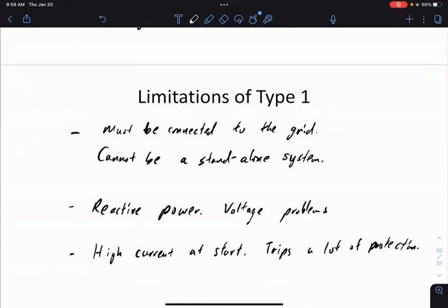Okay, so we have come a long way from these type 1 machines, right? This was really a proof of concept at that time, as you cannot put a lot of them in the system. Good. You can't create line power from a different one, right? You still need a reference. Right, you need a reference that's fairly constant. It can't just be another wind turbine, because that's also changing. So it's not a reference. You guys are sort of fighting each other. Right? So you need some constant reference for the first one.